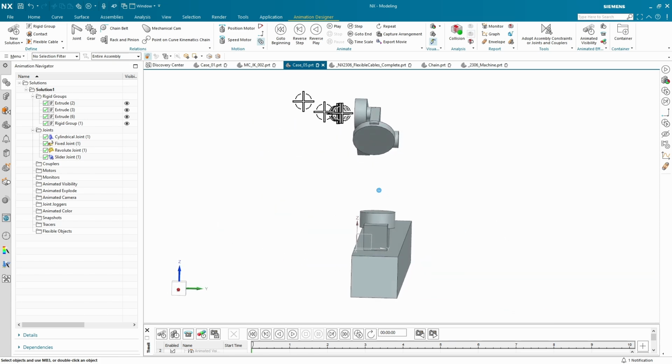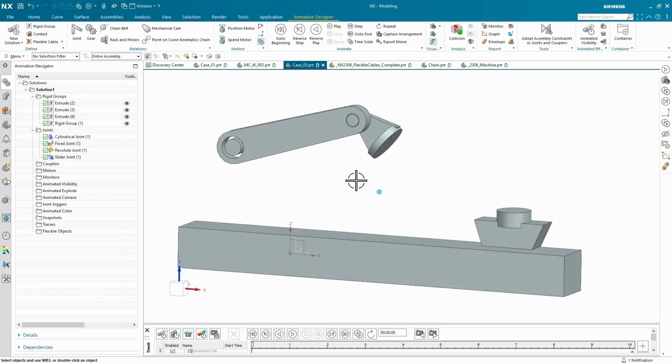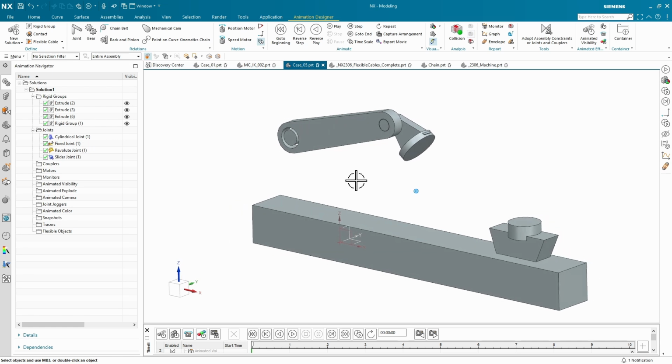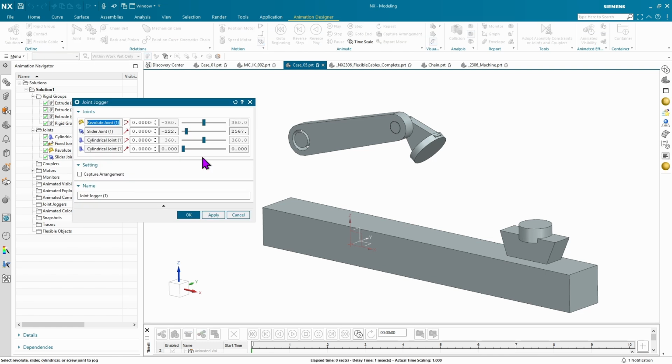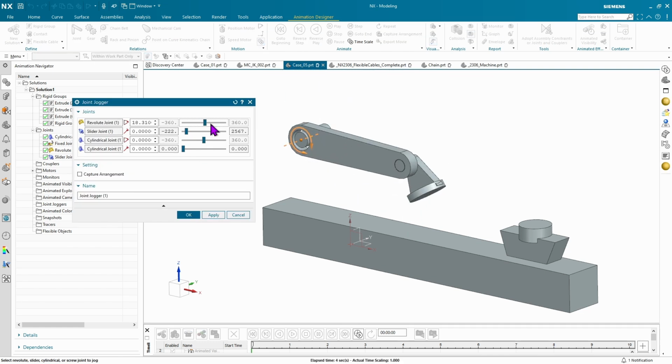view, the parts don't actually line up, and the rotation is going to have to get adjusted as well. One of my favorite things to do when evaluating a case to see if inverse kinematics will even solve is go to the joint jogger command and dance through some of the ranges of motion. We know it works that way.